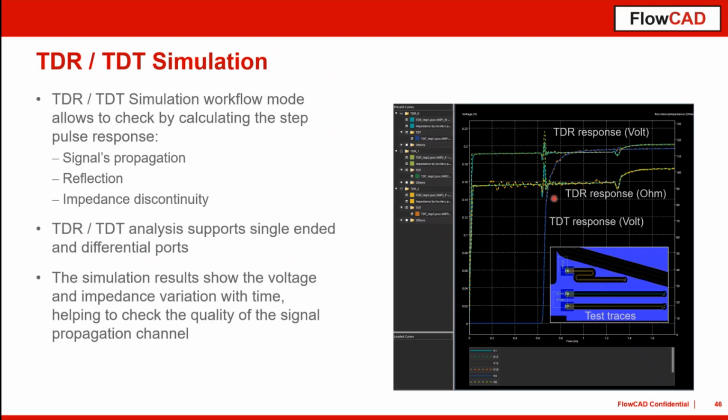But we also can see that we have an impedance mismatch caused by the transition from top to bottom. And it might be possible to optimize the via structure to improve the impedance profile. That is especially necessary when you run very high data rate signals like PCIe Gen 4 and 5 and so on. That must be very, very smooth. You have to make sure that you have a very smooth impedance profile on these traces.